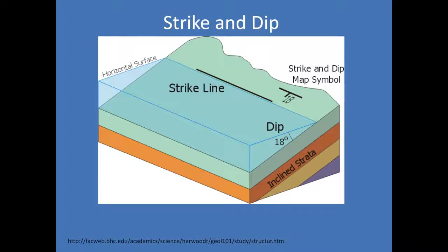Generally water flows downhill, and so the direction that those strata align with is also the direction of the regional groundwater. You'll see that the flow and direction of groundwater is also dependent on specific and localized changes in the geology, as well as the connection to the surface hydrology. But regionally speaking, groundwater flows in the direction of the geologic dip, which in our case is to the southeast.